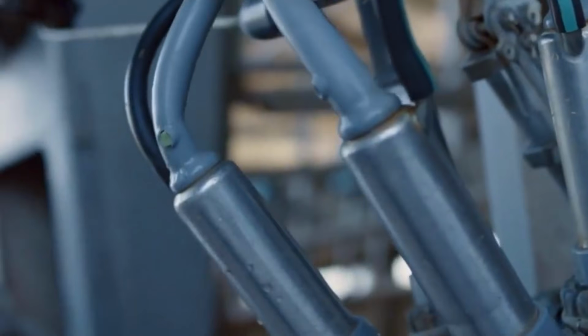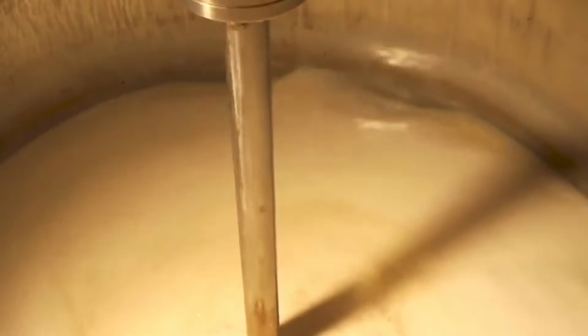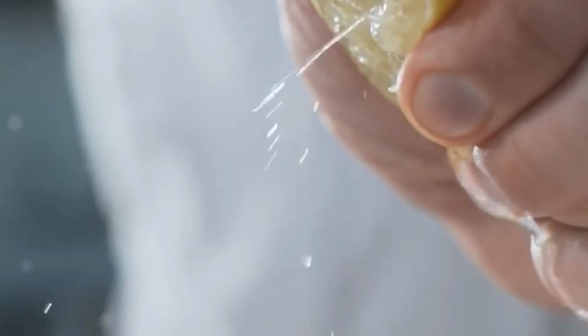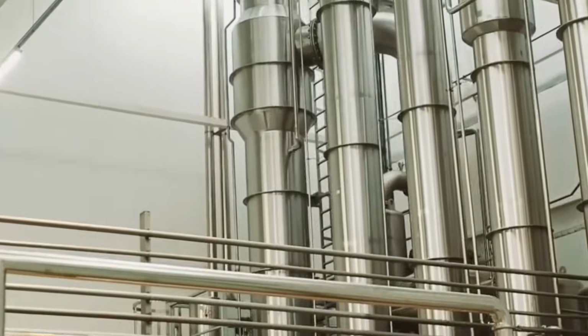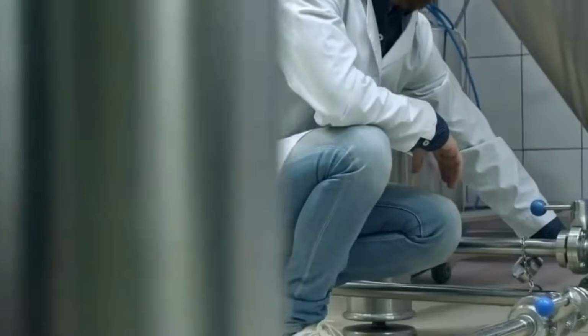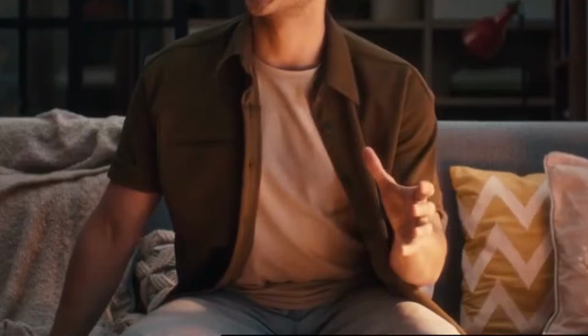Once the beverage stream is formed, it moves into a deaeration tank where vacuum pumps lower the internal pressure to remove dissolved oxygen. This step is critical to improve carbonation absorption and prolong product stability. The deaerated mixture then flows into a cooling module that chills the liquid to near 0 degrees Celsius using a glycol-based refrigeration loop. Lowering the temperature increases the solubility of carbon dioxide in the next step.